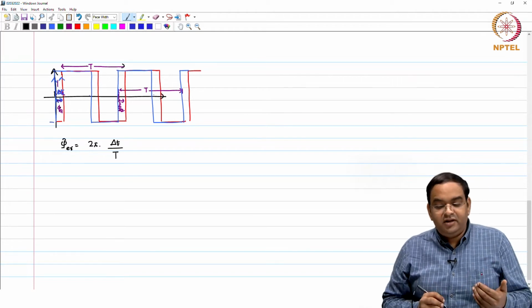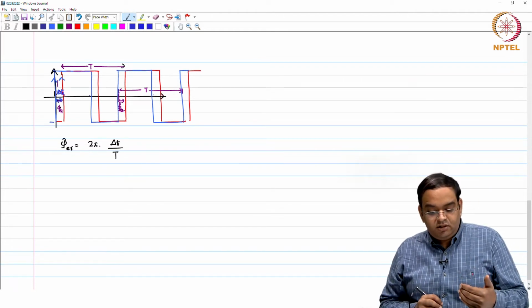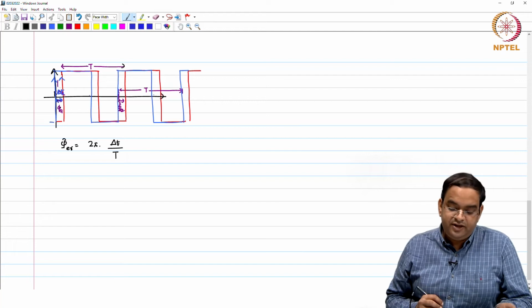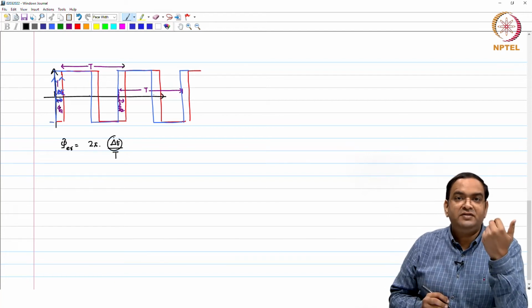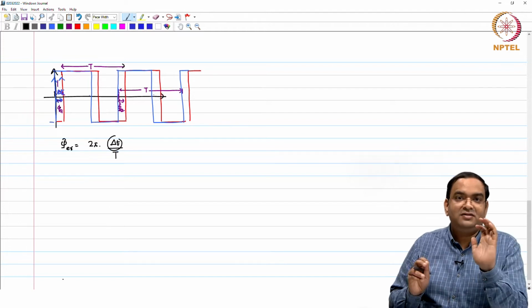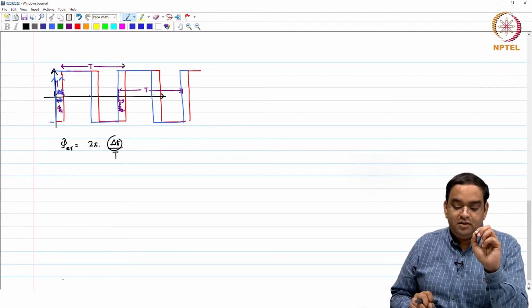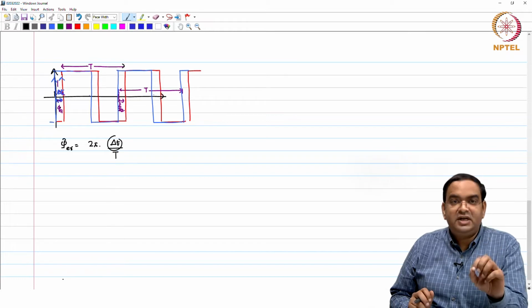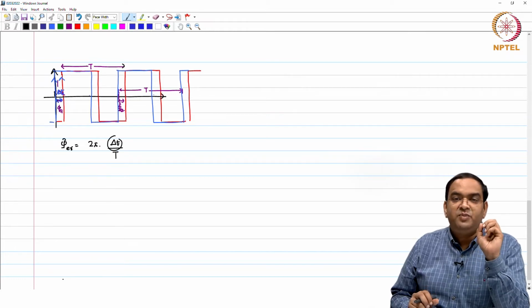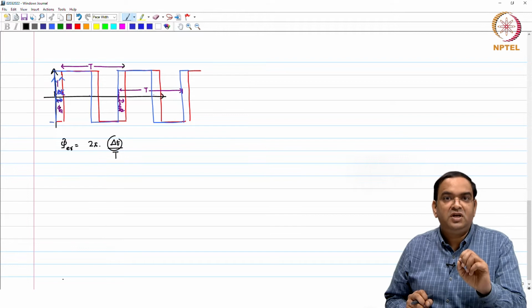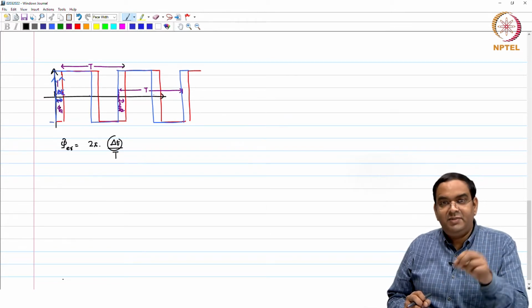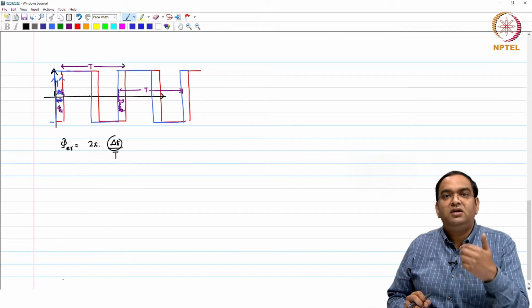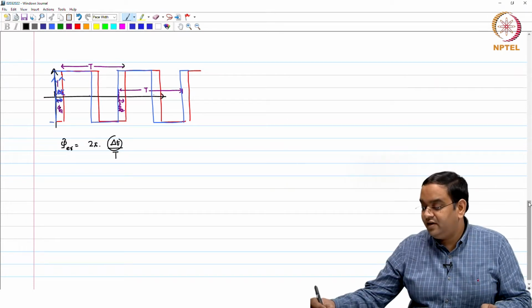Okay. So, here you see that as the time period increases, as your delta t increases, your phase error increases. This is an ideal representation of the phase error between two square waves. How the phase error detector is going to detect it and implement this, that is something which we will learn as part of the phase error detectors.